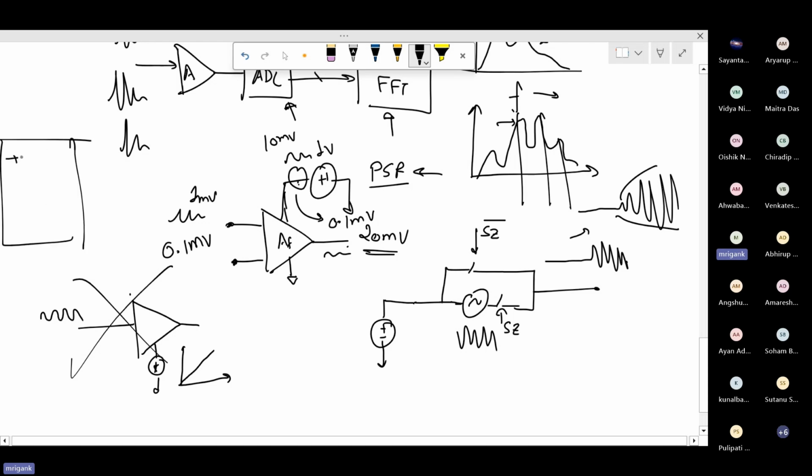You can look at the data. There will be some numbers in a sequence. So that data has to be fed to the LTSpice source. I mean, the piecewise linear file, you need to read that data. So I think directly it can read the CSV data also. You can just check. If that works, then we are done. We can directly use the CSV data also.